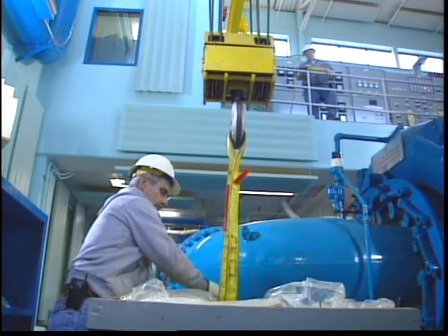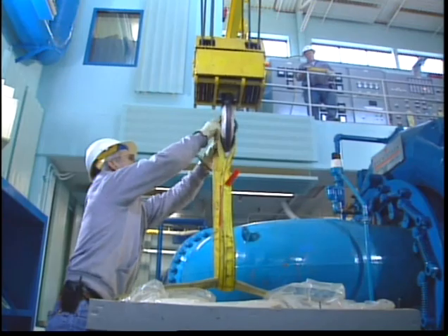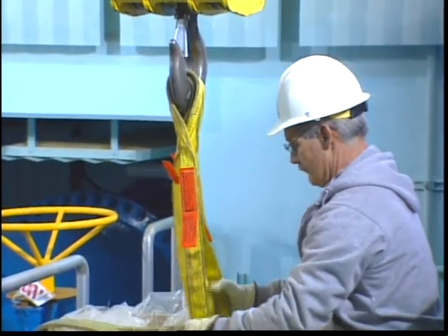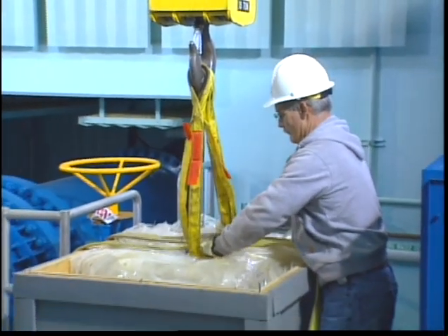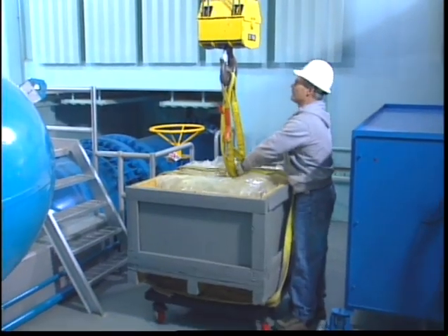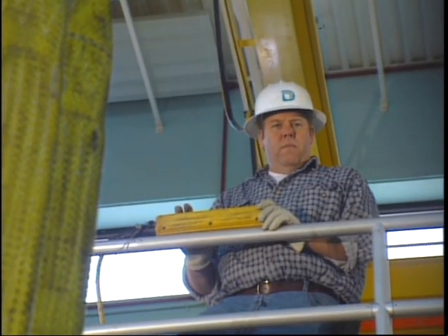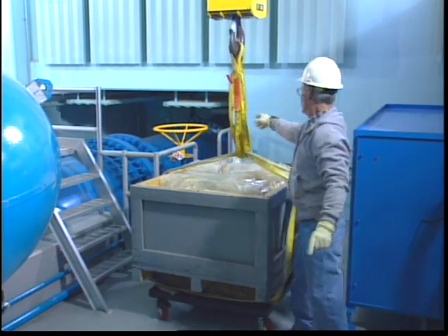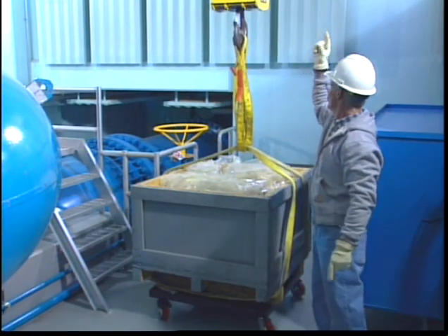Make sure slings and straps aren't stretched or frayed, and never try to splice a broken strap. Any unused straps or slings should be secured so they don't drag behind while the load is moved. Riggers should keep their hands and feet away from the load when slack is taken out of the sling. All riggers should step back away from the load as it's first lifted.